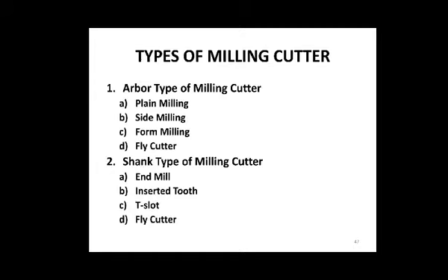Milling cutters are cutting tools typically used in milling machines or machining centers, and occasionally in other machine tools. They remove material by their movement within the machine or directly from the cutter's shape. A variety of grooves, slots, and pockets in the workpiece may be produced from a variety of tool bits. Common tool bit types are square end cutters, ball end cutters, T-slot cutters, and shell mills.